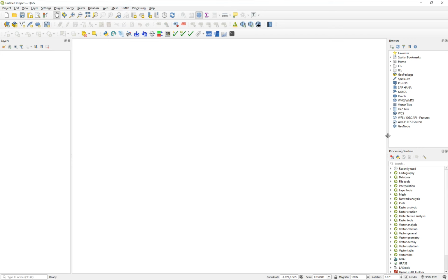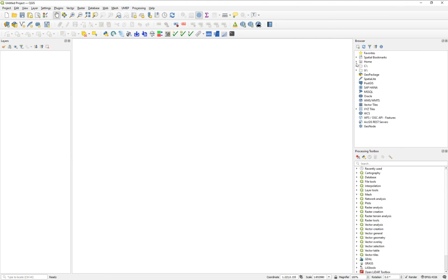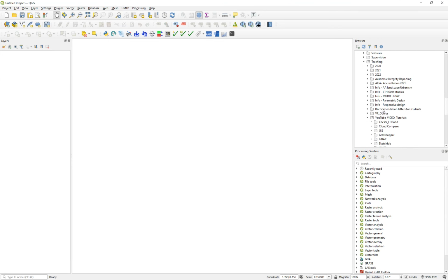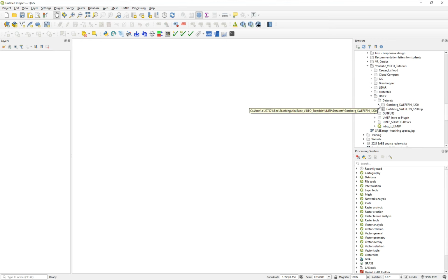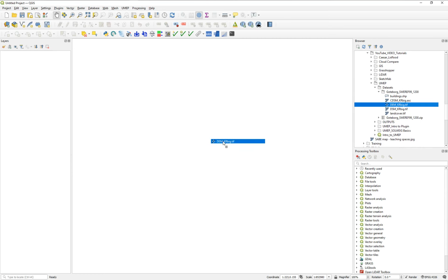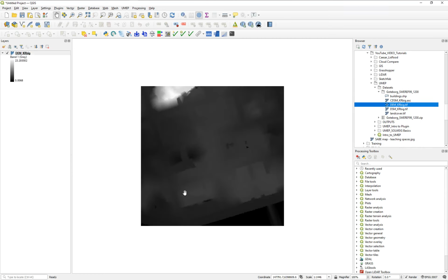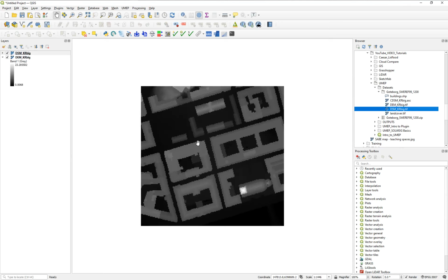Check my previous video on how to install. We go to our folder. This is UMEP folder, datasets. So we start adding the data. As I showed you before, we start with the DEM, which is the elevation of the ground. Then we go to the DSM, which is ground plus buildings.